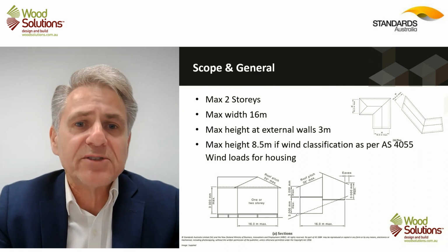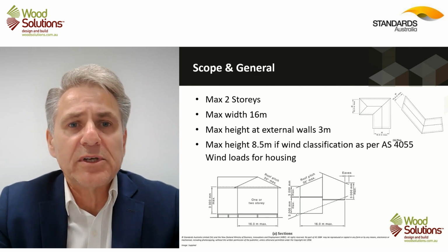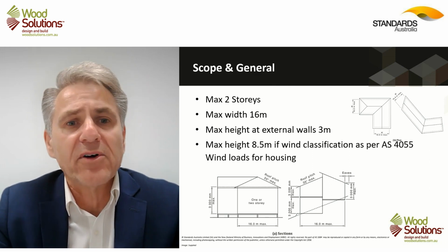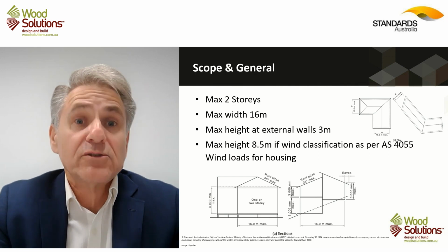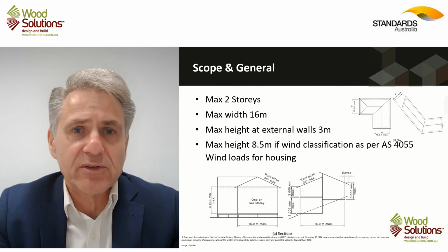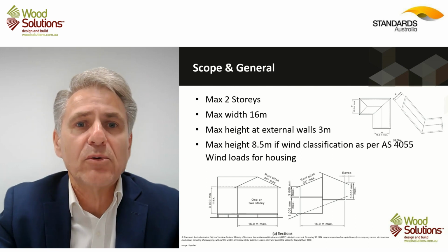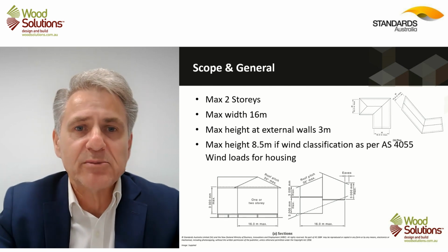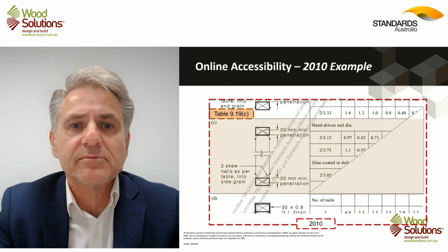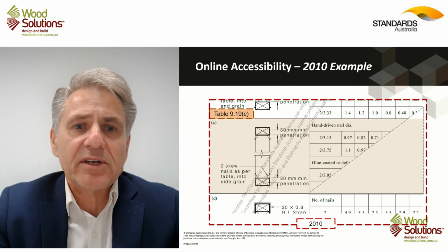And the key reason for that 8.5 metre height is that we use AS 4055 wind loads for housing for the generation of the wind loads on our structures within AS 1684 for our bracing type elements and tie down requirements.